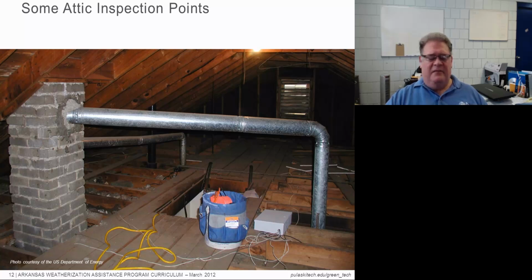Okay. Is the bypass that's created, do we have air path this way, in and out of the house or in and out of a wall in the house? If we do, that should be blocked off. How about plumbing vents? Here we have a big plumbing vent coming up. How about damming around the attic hatch? Okay, here we have an attic access. If we start blowing insulation in here, we're going to have it pile on top of the attic hatch or fall through.